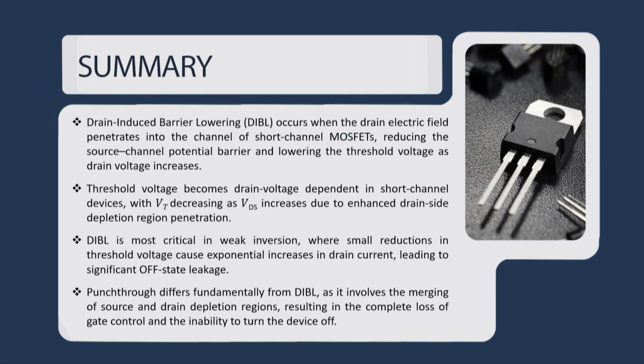So, let me summarize this lecture. In this lecture, we extensively discussed drain induced barrier lowering, which is a very important short channel effect, needs to be discussed, as the threshold voltage now becomes a function of VDS. We said that when you plot a conduction band, there will be a barrier lowering at the source channel junction, which is a function of VDS, because the applied drain field will penetrate through the channel and ultimately alters this barrier and significantly influences the threshold voltage.